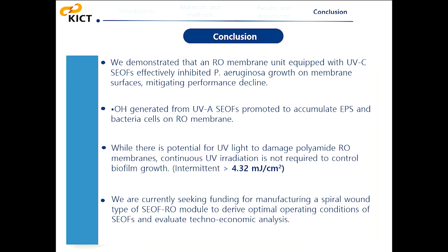To conclude my presentation, we demonstrated the reverse osmosis membrane unit equipped with UV-C side-emitting optical fiber to inhibit the biofouling of the membrane surface. And also, the hydroxyl radical generated by the UVA side-emitting optical fiber promoted accumulation of extracellular polymeric substances and bacterial cells on the reverse osmosis membrane.